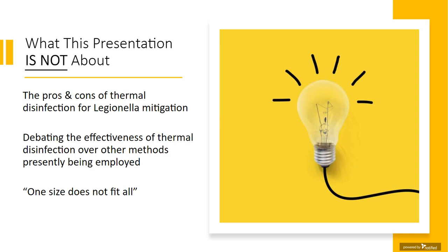One of the things I've learned over the last couple of years regarding Legionella mitigation is that typically more than one solution is required to have an effective Legionella mitigation system. So it's not just thermal disinfection or chemical flush or filtering. You need to basically combine different approaches to really optimize your Legionella mitigation.